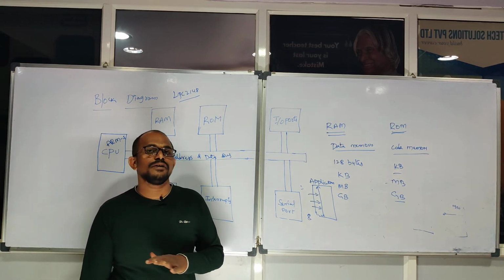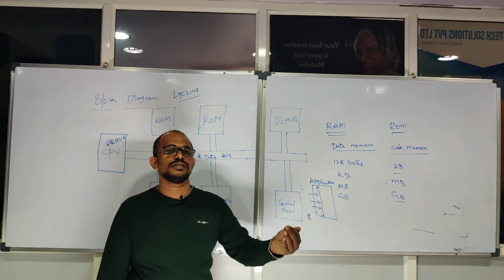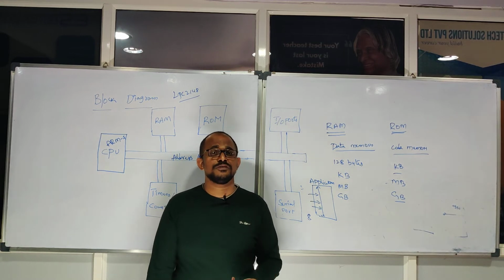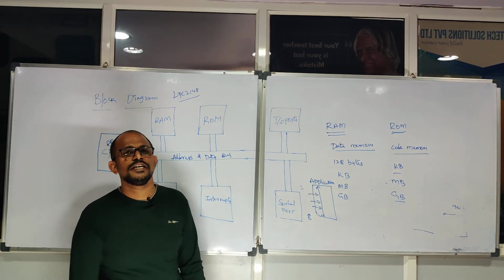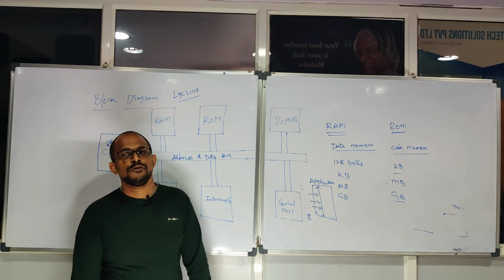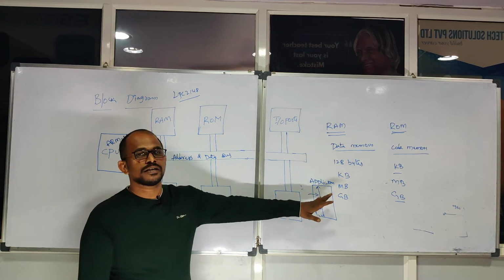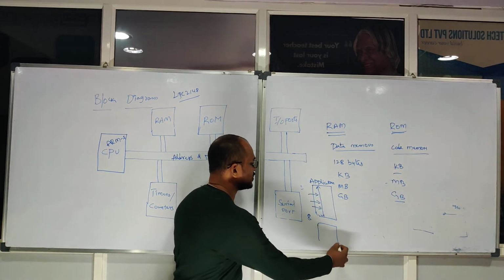Okay, so it never takes care of whether the middle condition, the third condition, or the fourth condition is the priority. So how do we overcome these kinds of situations? You can use interrupts. An interrupt is designed so that if you have any high priority task from the application, you can stop the current running process and divert it for ISR execution.